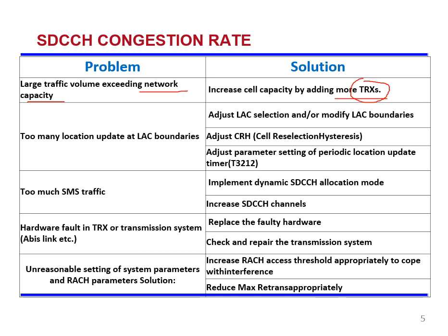What are TRX? TRX are nothing but transceivers. These transceivers are the capacity building blocks of any base station, of any BTS. The more the number of TRX, the more the channel carrying capacity, the more channels it can cater to. So if the traffic volume is increased, one of the methods you can follow is to increase the number of TRX, if it's feasible.